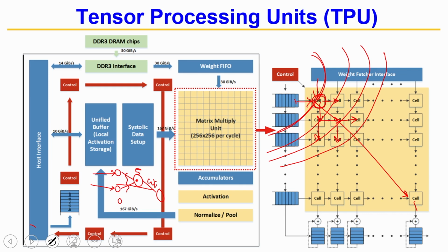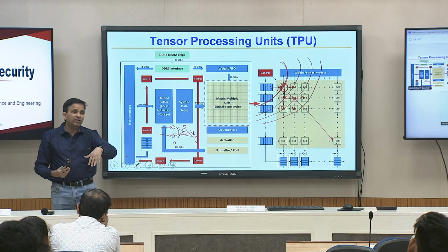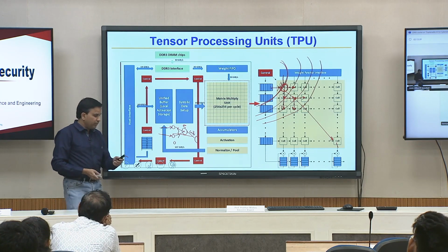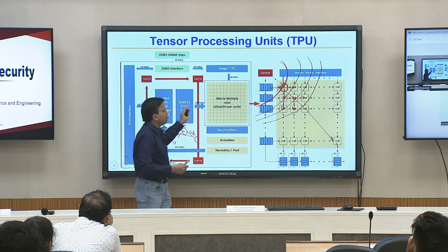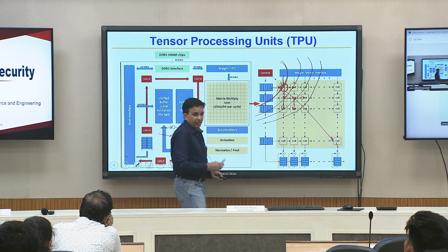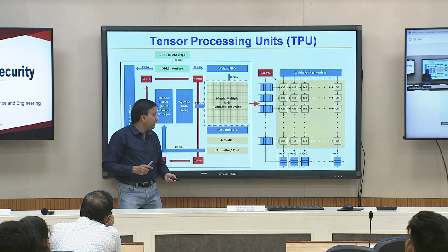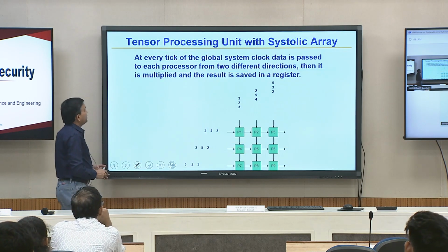Then the result, whatever the decision, slow down. What is the decision in the car? Either apply the brake to maintain the distance, or if it is an upslope, increase the fuel injection to maintain the cruise controller speed, for example. Or if you are going down, then decrease the fuel injection rate so that it does not speed up beyond what you asked for in your cruise controller. So those are the aspects, but I zoomed in only into the middle part. Any question on this? Now I will show you, I hope this animation will work.